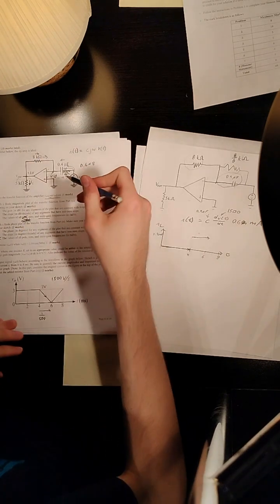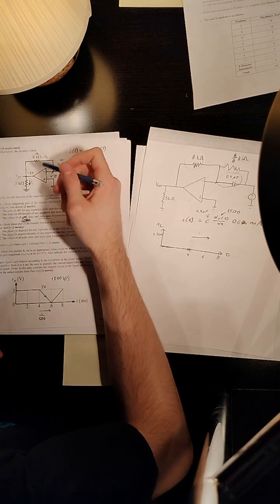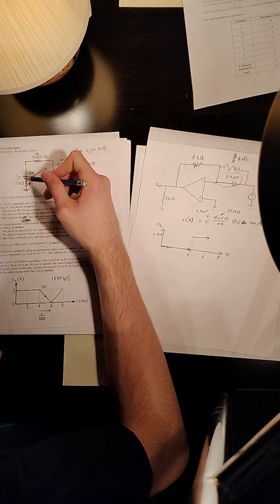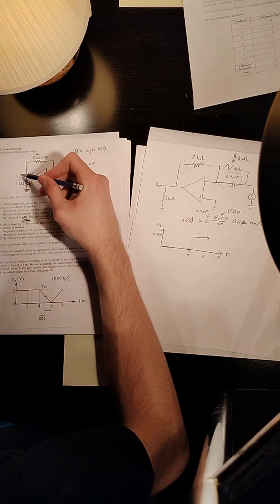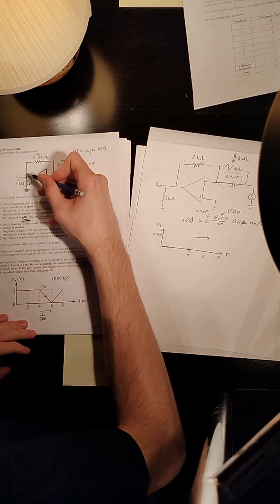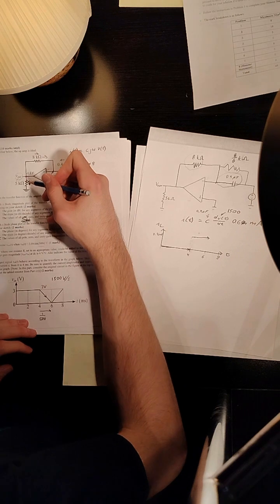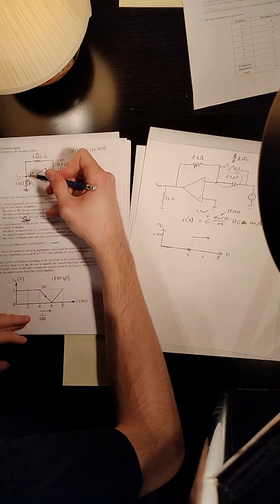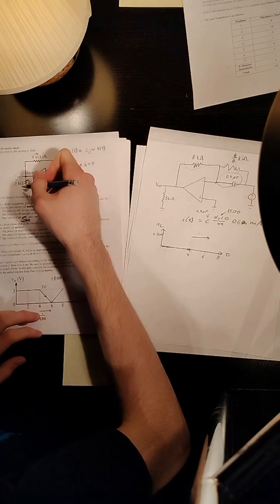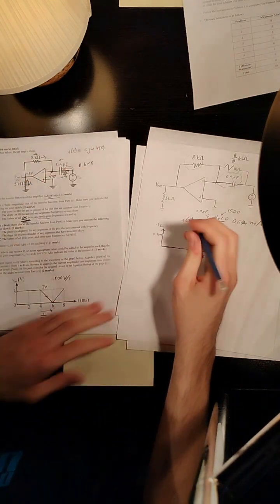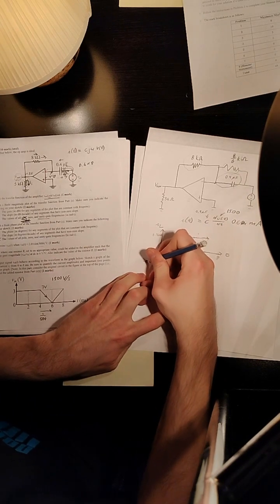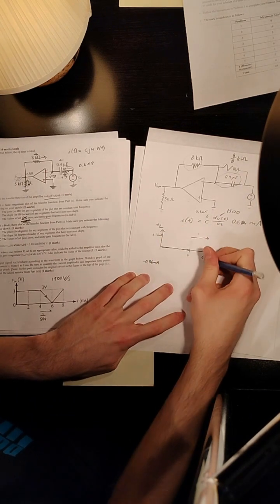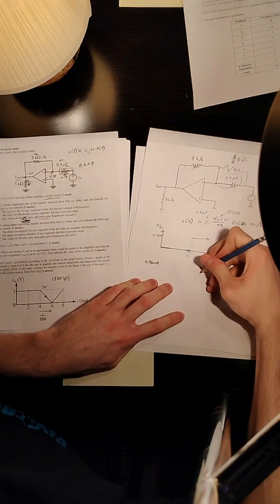So I would argue that your current should just be the opposite, and therefore your voltage here would be negative 4.8, which means that current goes this way. And so your IL is negative, but it would be the same magnitude. So you'd get negative 0.96 milliamperes, and your current would look like that.